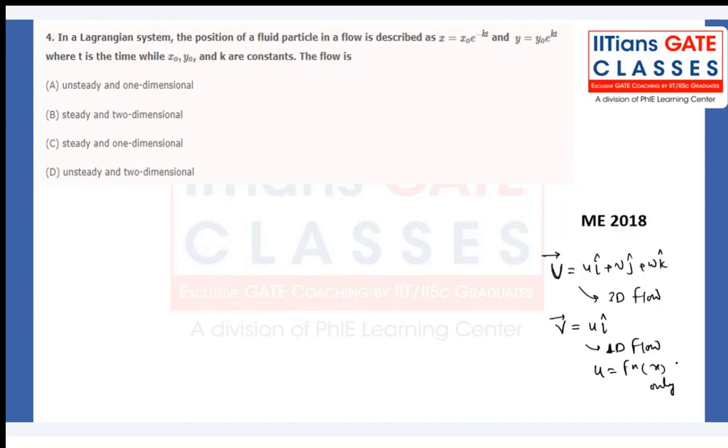No, why should we introduce the polar system in a rectangular duct unnecessarily? We know that rectangular means Cartesian will follow, right? Now, the velocity in the Lagrangian system is being given as something like this. That is a Lagrangian way of discussing, because it is telling you the past history of the fluid particle, at what time the position of the particle, and that we are not doing here in the Eulerian descriptions.